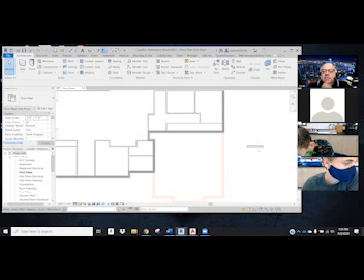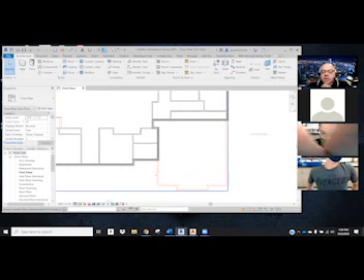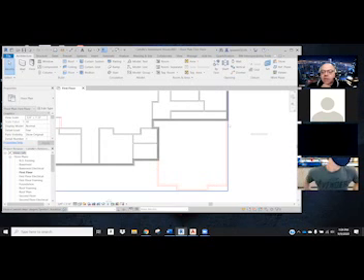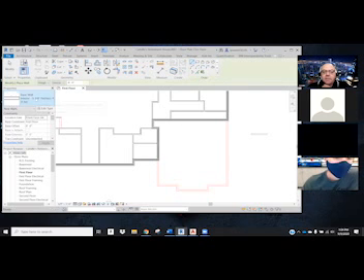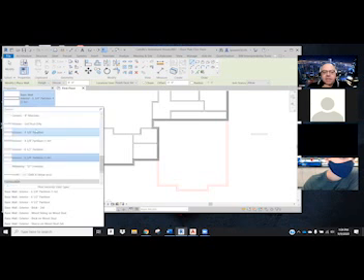Now we're gonna leave that sitting there for just a minute. And you guys can go, what the freak? I want you to now finish the exterior walls of your garage with the same wall that you did your perimeter of your house with. So whatever you drew your house with, finish out the garage. So in my case, I used the brick. So I'm going to switch to my exterior wall.